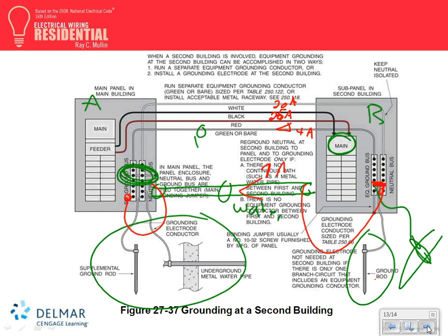This is very important. This can apply to a shed that you have, to a garage, or to a 50,000 square foot building that's fed from this building. So moving forward, I don't even like, guys, to mention that you can bond them. Moving forward, you do not bond. New installation, this is off. You still need to establish your grounding system.